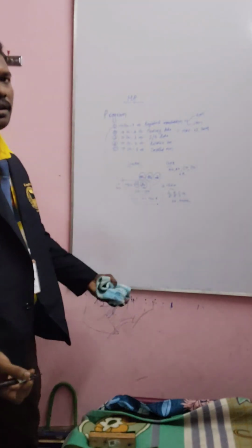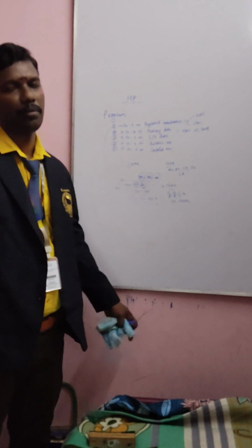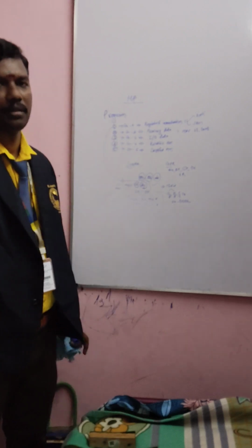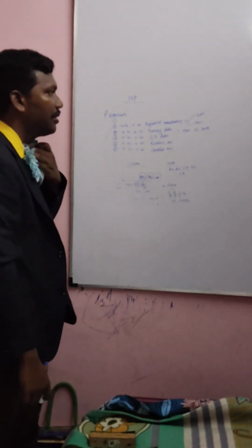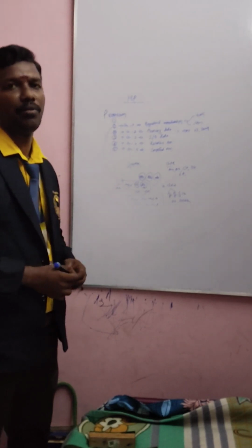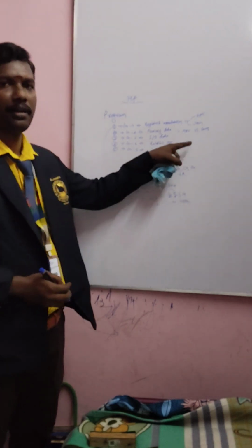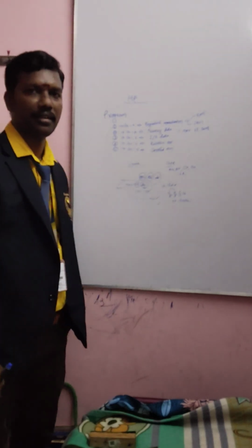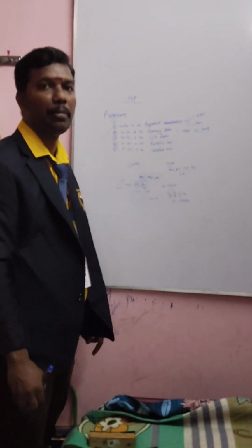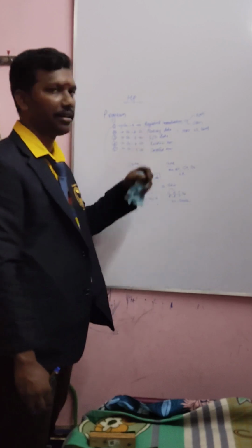If I write MOV SI, 4200H, no issue on that. It will be represented as 16-bit data. But what is it saying with MOV SI, bracket 4200? What does it mean? MOV is the operator, SI is the source index register and the destination register, and this is the representation of memory. This is the memory addressing mode.